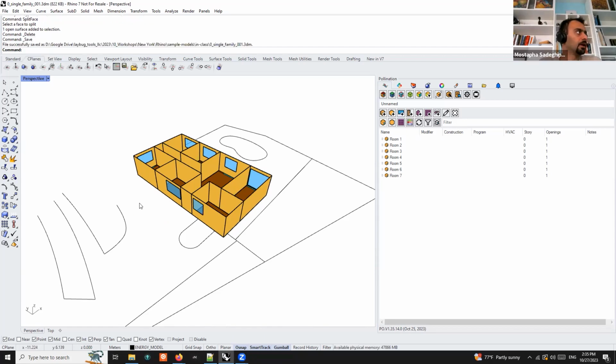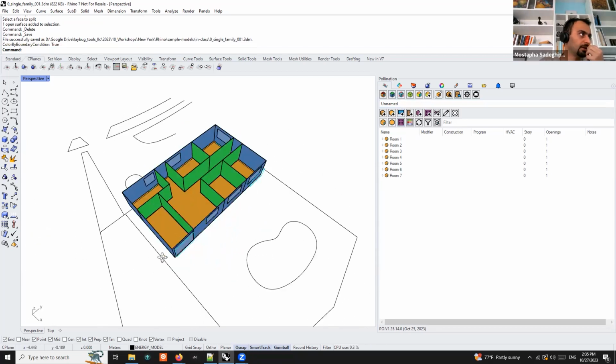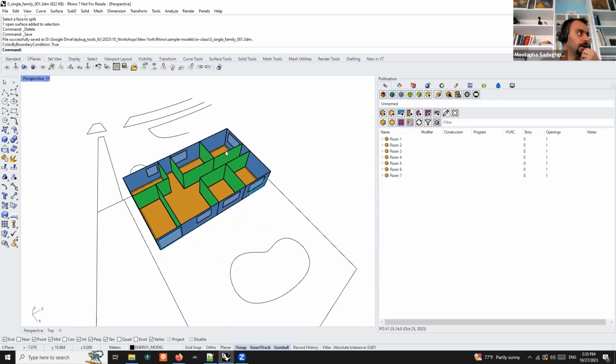Okay. So with that, now we have this. I went here, clicked here. You can quickly check all the interior faces. In my case, I drew them correctly, so they're matching. Does anyone see a blue face here? If you see that, then probably you have to go and fix your drawings for the rooms.